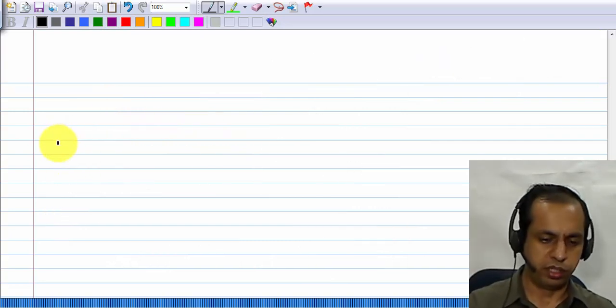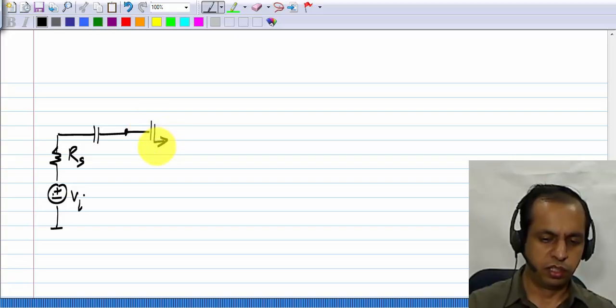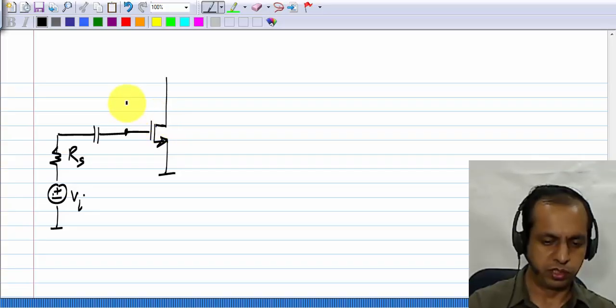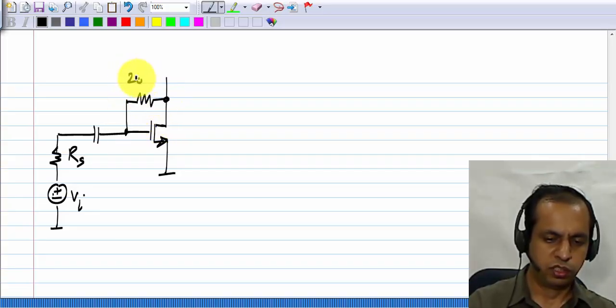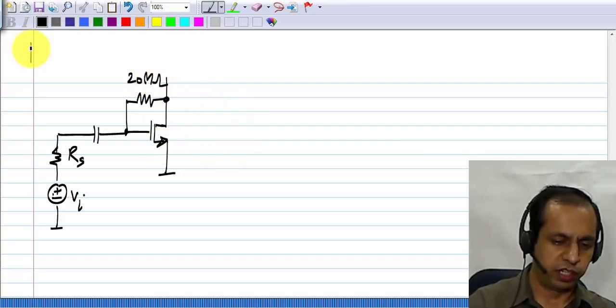By now you should be quite fluent with calculating the operating point, writing down the small signal picture and doing those calculations on the small signal incremental circuits. So I will go quickly through those parts and spend time on the actual calculation of the swing limits. And also, because we've been using the same transistor parameters, in fact, I didn't even mention that.